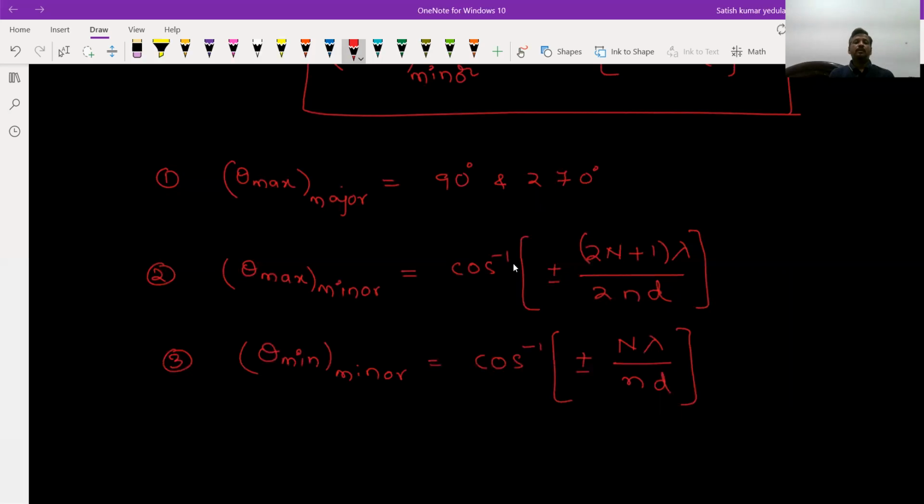And there will be another angle that you have to find out, which is the first null beam width. You will get an expression for that. From that, you will get half power beam width. Then by taking a particular value of n, let's say n equal to 2, we have already done it. Let's say n equal to 4 and d equal to lambda by 2 case, we will try to find out the radiation pattern for this 4-element array. Because it's going to be very lengthy, I'll be stopping this lecture here.